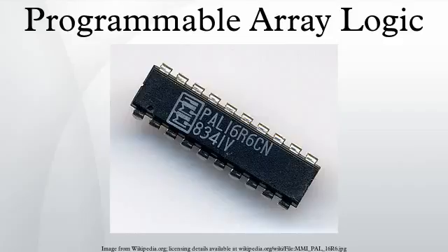Early history: before PALs were introduced, designers of digital logic circuits would use small-scale integration components, such as those in the 7400 series TTL family. The 7400 family included a variety of logic building blocks, such as gates, multiplexers and demultiplexers, flip-flops and others. One PAL device would typically replace dozens of such discrete logic packages, so the SSI business went into decline as the PAL business took off.